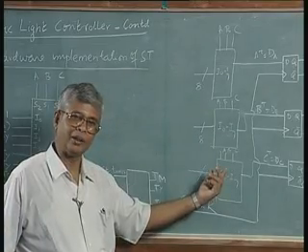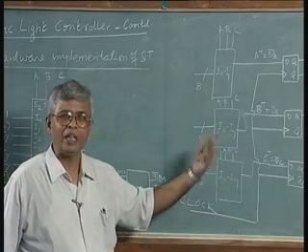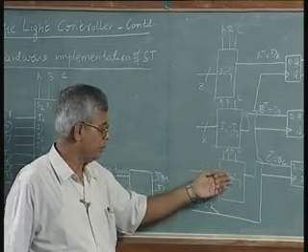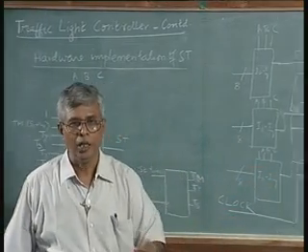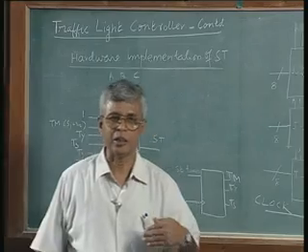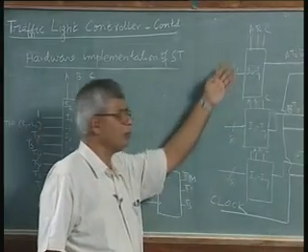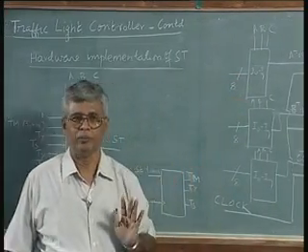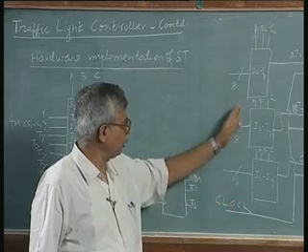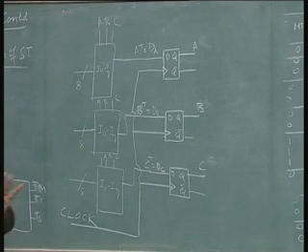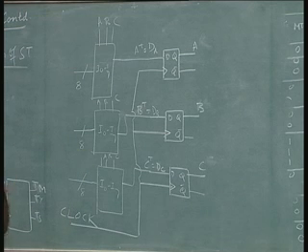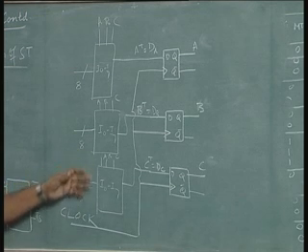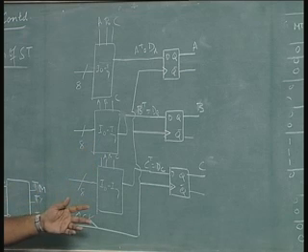The size of the multiplexer depends on the number of states. Up to 8 states, multiplexer will be 8 to 1. Up to 4 states, multiplexer will be 4 to 1. Up to 16 states, multiplexer will be 16 to 1, like that. And then the inputs of the multiplexer are the only thing which is different from problem to problem. To that extent, it is a very simple design. It is all fixed except to find out this. That will be written directly from the ASM table. That is what I am trying to say.